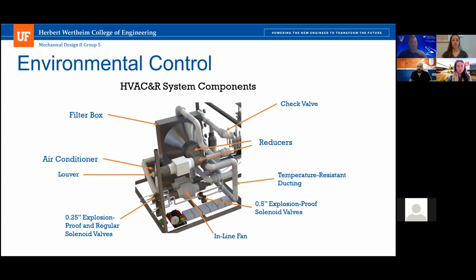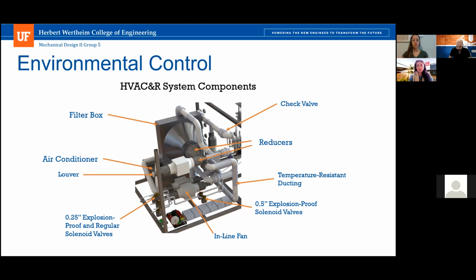Both chambers contain a dual temperature and relative humidity sensor and gas sensors that are capable of detecting the 5 primary gases required by the customer needs. Both chambers also include a PTC heater with a fan that is oriented so that its fan sucks in the cooler air from the bottom, heats it up, and passes it out at a higher temperature upwards.